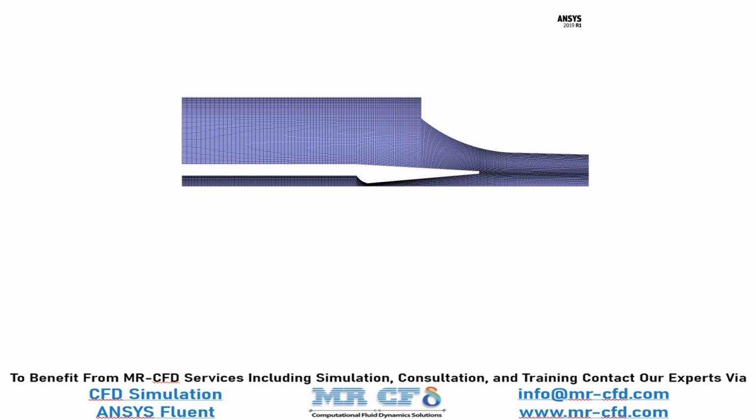The mesh type is unstructured. Due to the sensitivity of the fluid to the cross-sectional area, manual meshing was used at each of the defined edges to increase mesh accuracy at more sensitive points. Face meshing has also been used to uniform the structure of the mesh.